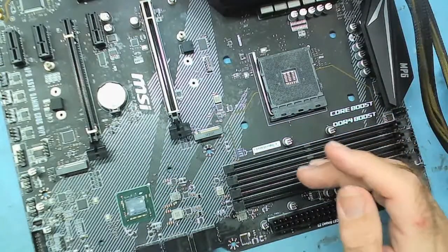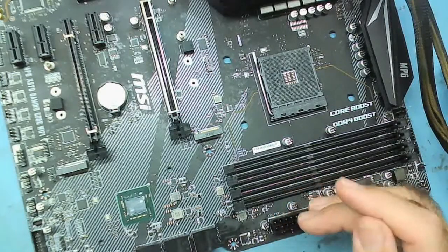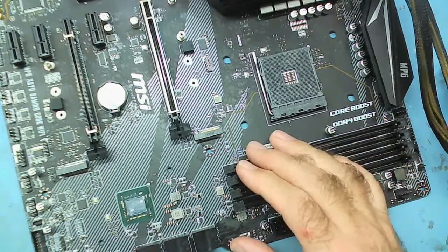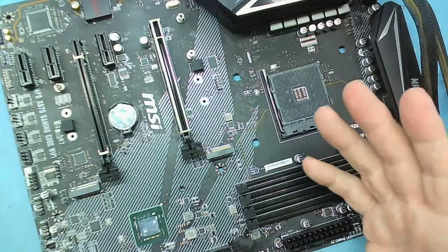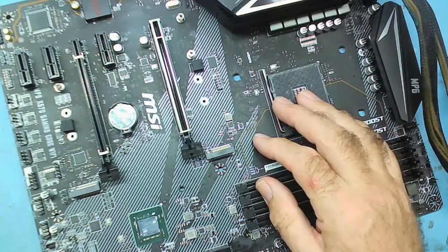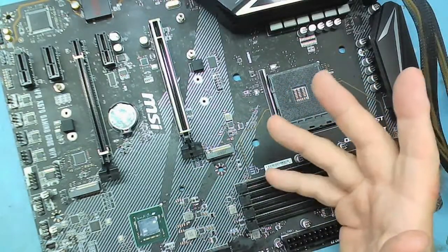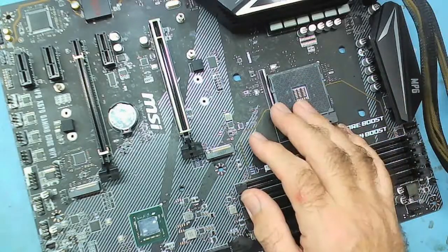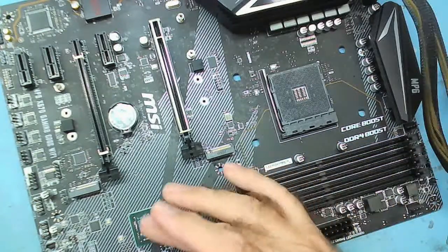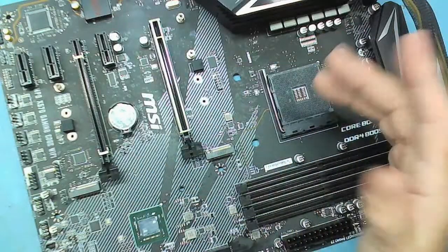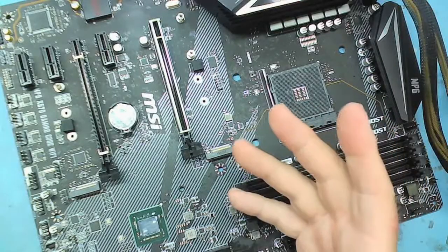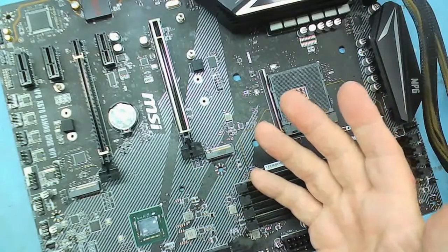Let's think about this. We've got a fault. It's most likely the fault is on one component, which tells us that either we've got one regulator that takes the 5 coming in and gives 3.3, 1.8 and 1.1, and the regulator's faulty, so only the 3 volt output's generating properly. Or we've got more than one regulator, so you've got 5 coming in here, you've got a regulator for the 3.3, the 1.8 and the 1.1. But there's 2 of them that aren't working. So there could only realistically be one fault. I mean, there could be more than one, but it's not so likely.